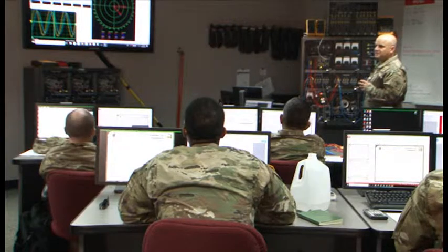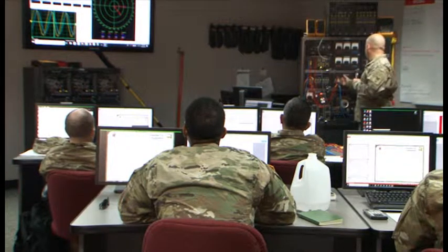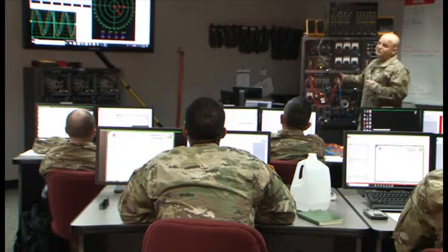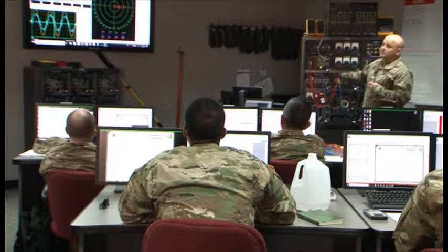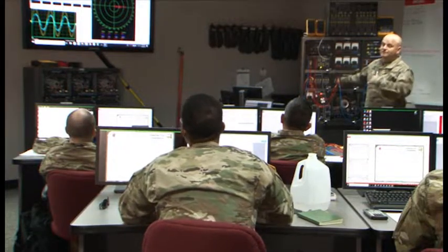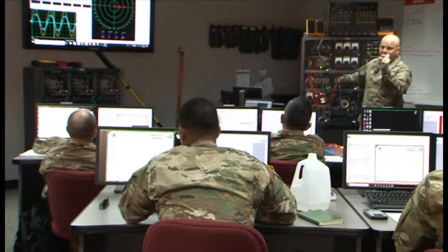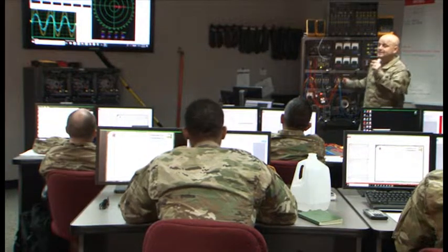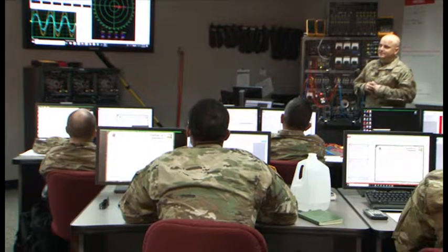Okay? There's going to be a pretty big difference there between the S and the P, right? But the moment I add the same amount, or let's just say some fractional amount of capacitance, not only did I shorten my current vector, but I brought it a lot closer in phase relationship back to that reference, which is thereby reducing the phase angle between voltage and current, which is then in turn going to reduce that line current. Make sense?